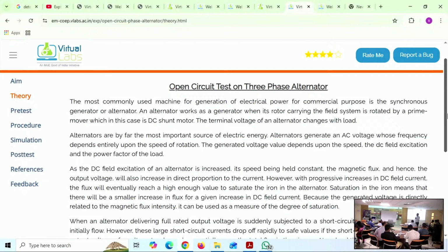Accuracy, how accurate. For a low resistance load, what range is this ammeter reading? If you connect low resistance loads, then the ammeter should be connected nearest to the load, because currents must be accurately measured. If you are measuring high resistance loads, voltage must be accurate. So the voltmeter should be connected close to the load.